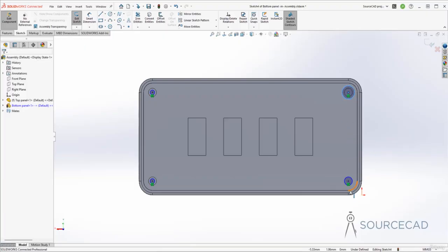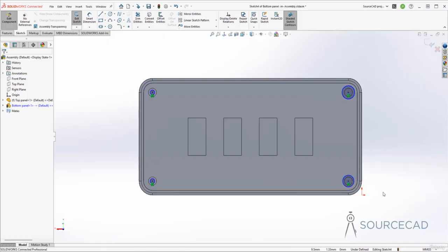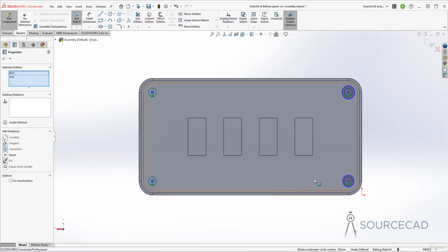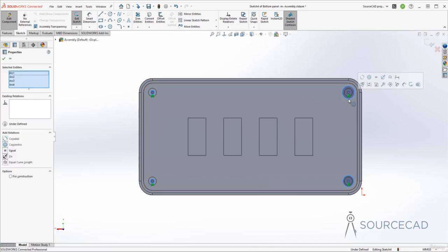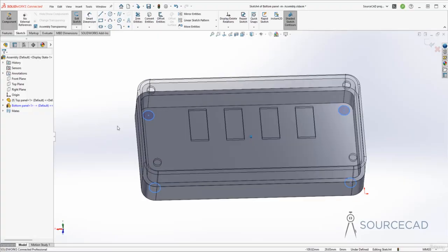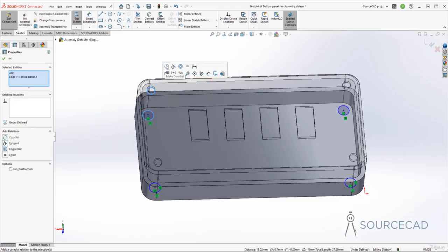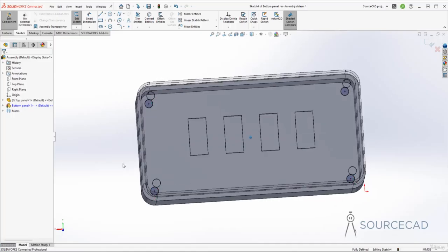Now in this case, we ended up making this one coincident, or maybe not. No, it is not coincident on this one. So that's totally fine. Now what we are going to do is we'll just add the equal constraint. So I'll select it all and I'll click on make equal. So now they are all equal and let's just orbit it slightly, select the circle and then select this edge or the bottom edge. Any edge is just fine. And then make it co-radial. And now they are all of equal radii. All right, so that's done.